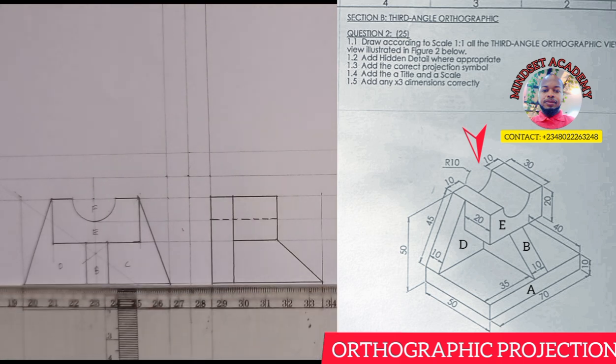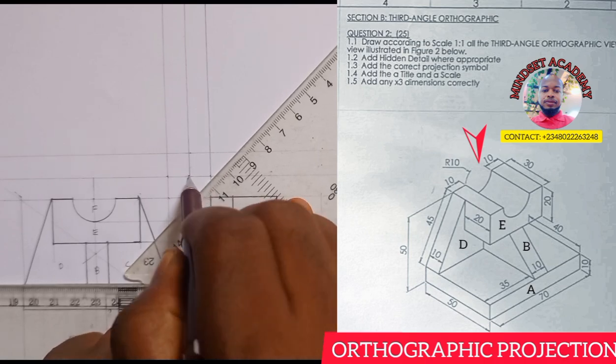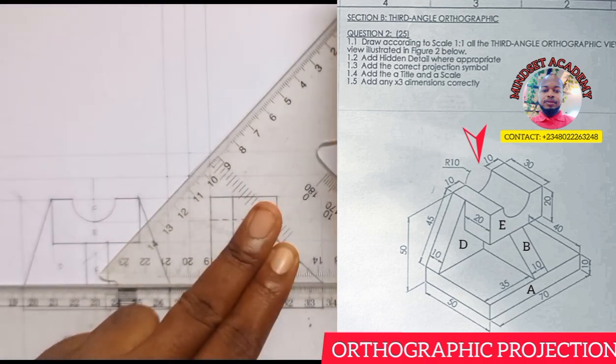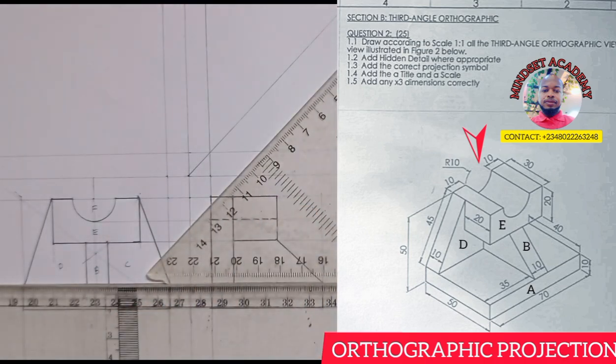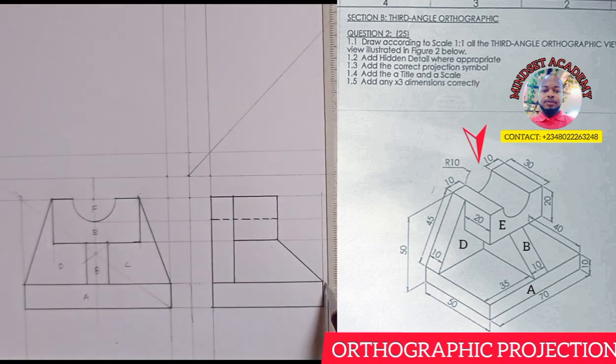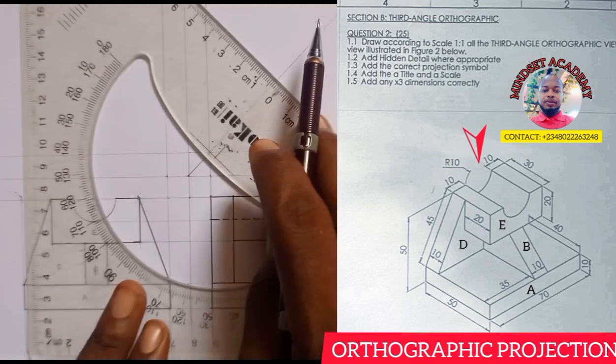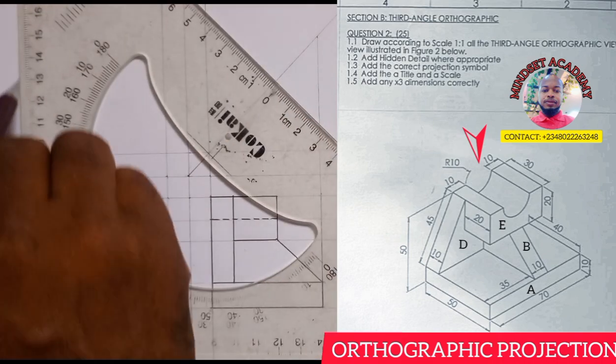you just come to the end elevation here, where all the middle point here, and you draw an angle of 45 degrees. And you now project each of those edges. When this one touch this, and you come here also, you project this too, and this one touch this.